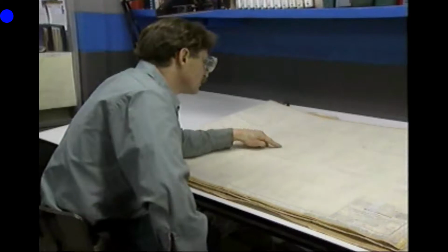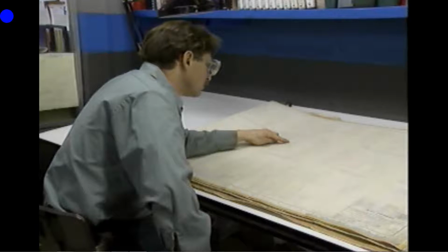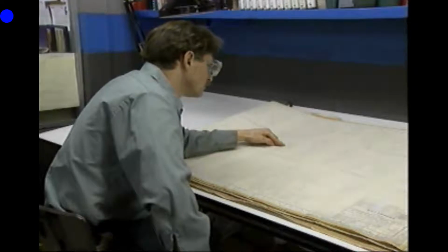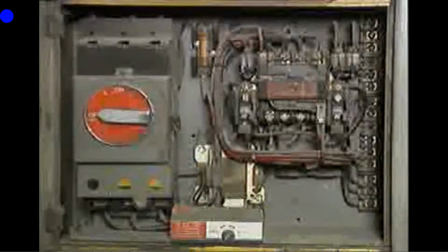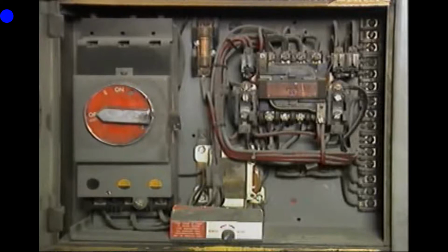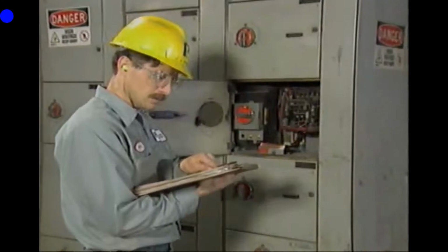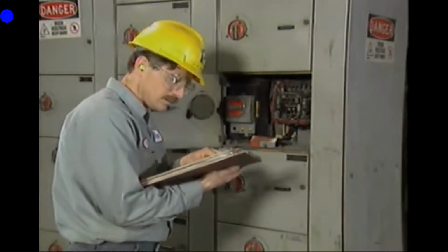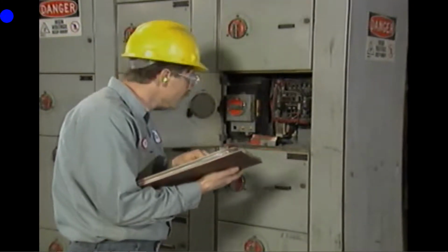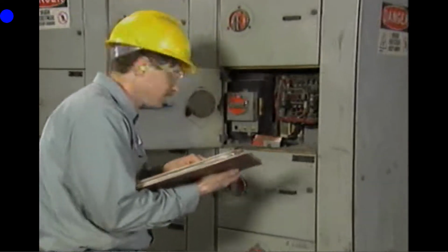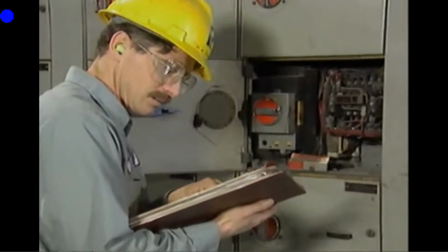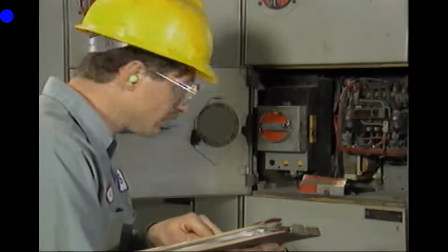The controller's schematic diagram is generally used during the evaluation process. The schematic shows you what the components are, how they're supposed to operate, and how current flows through the controller. With the schematic, you can compare what is happening with what is supposed to happen. That way you can eliminate any components that are working correctly. After the possible causes of the controller malfunction have been narrowed down, the components that have not been eliminated should be carefully inspected. You can use the motor controller's wiring diagram as a guide to locate each component.